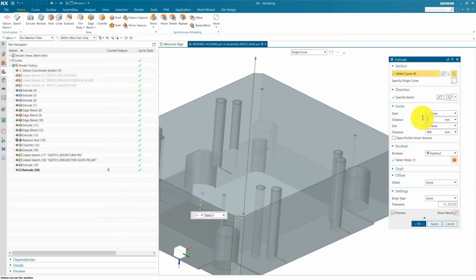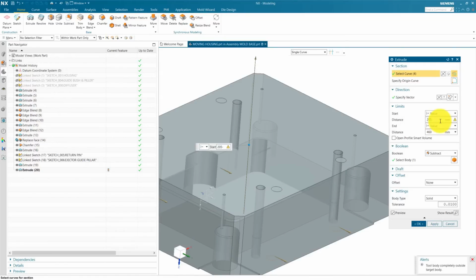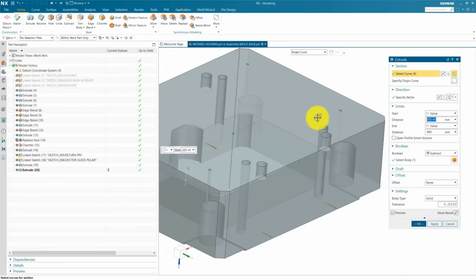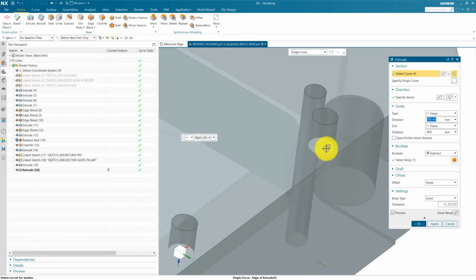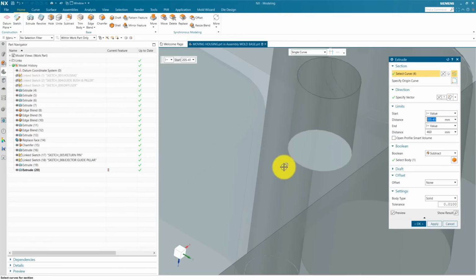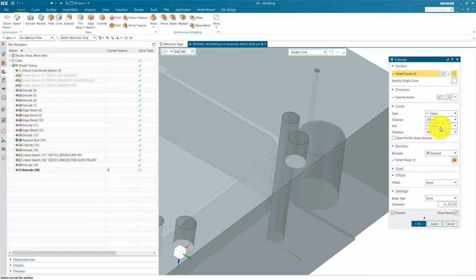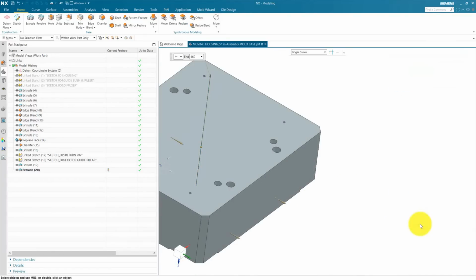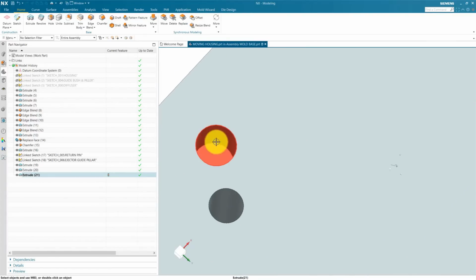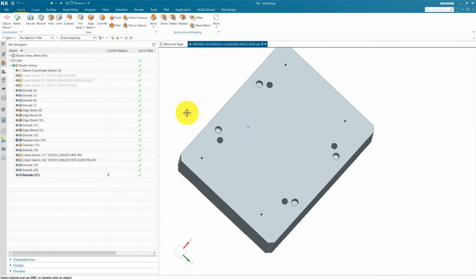So our starting limit is 105. We reach at top. When we minus 41, we can create a 41 mm deep hole because that is the starting limit. The ending limit we can use anything outside the moving housing. Press OK. Now we need to add some bolting hole inside this for the ejector guide pillar.